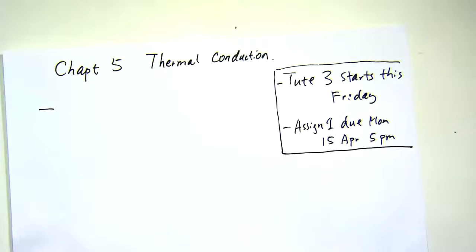So some of the physical understanding of thermal conduction: we said that conduction requires a certain medium in order to happen, a medium so that the thermal energy can pass through. Without that medium, the heat cannot be transferred in the form of conduction. It can happen in terms of radiation if the radiation waves or the passage is not blocked, but the medium is the requirement for conduction to happen.